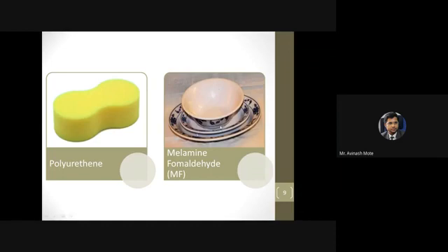Because ceramic material will not give you a quality surface finish or this type of texture or design, which is required mostly in household applications. You can see it at your home also. Just break that particular bowl and you will find a different layer on the surface and a different material inside. That surface layer is made from melamine formaldehyde, a special purpose plastic used mostly for coating because of the good surface finish.